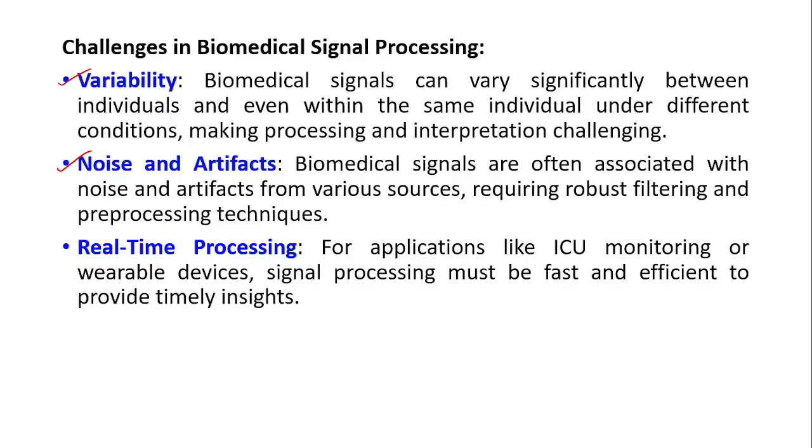Noise comes automatically from the environmental interaction of your signals. For example, if I am acquiring the signal near a power line, there will be power line interference. That is noise, not due to my error. But if I move and the electrode moves, that noise is an artifact.